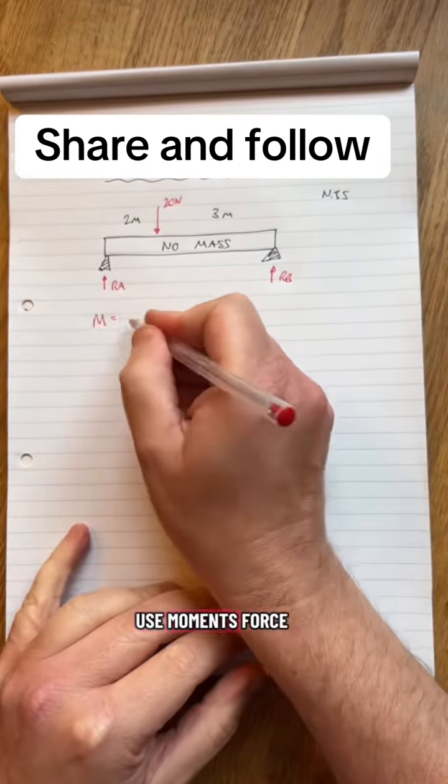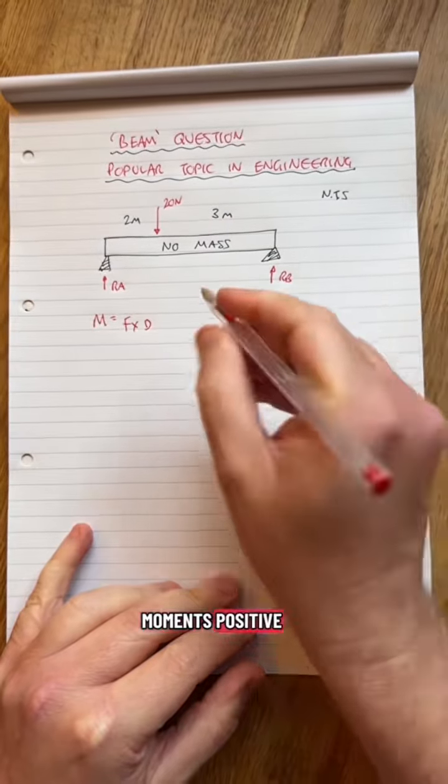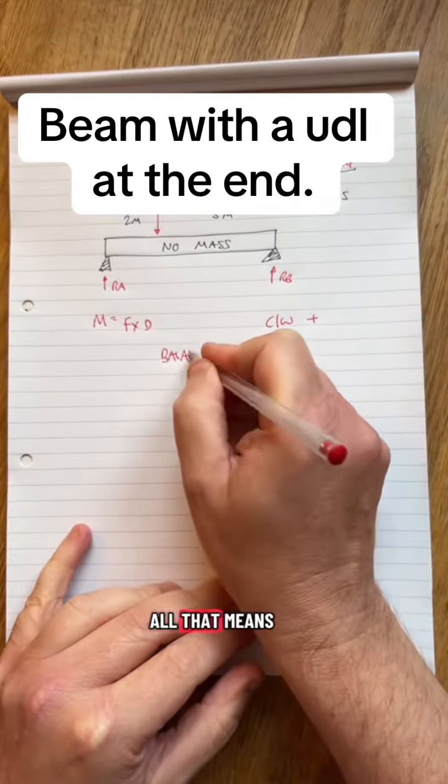So I'm going to use moments, force times distance. I'm calling clockwise moments positive. And this beam is in balance. I'm going to have balance down here. All that means is everything adds up to 0.